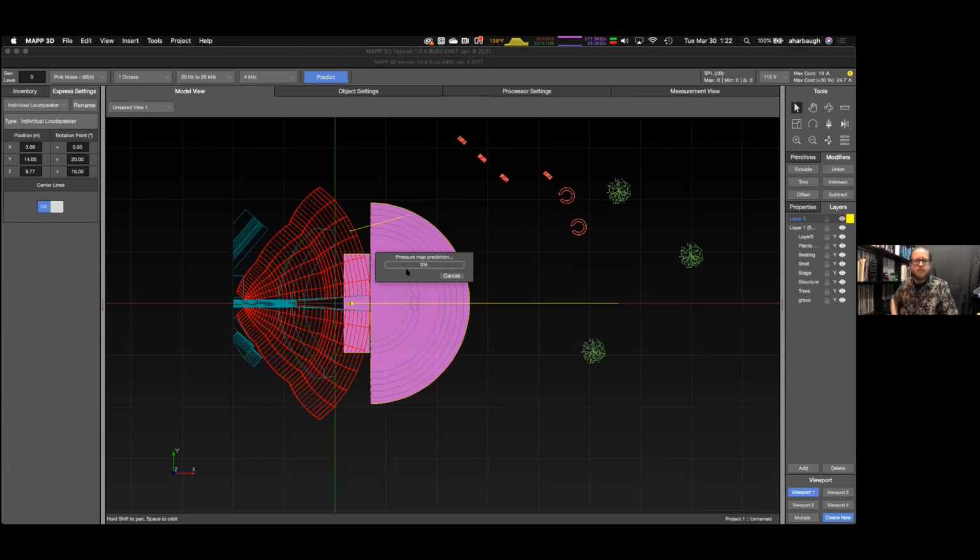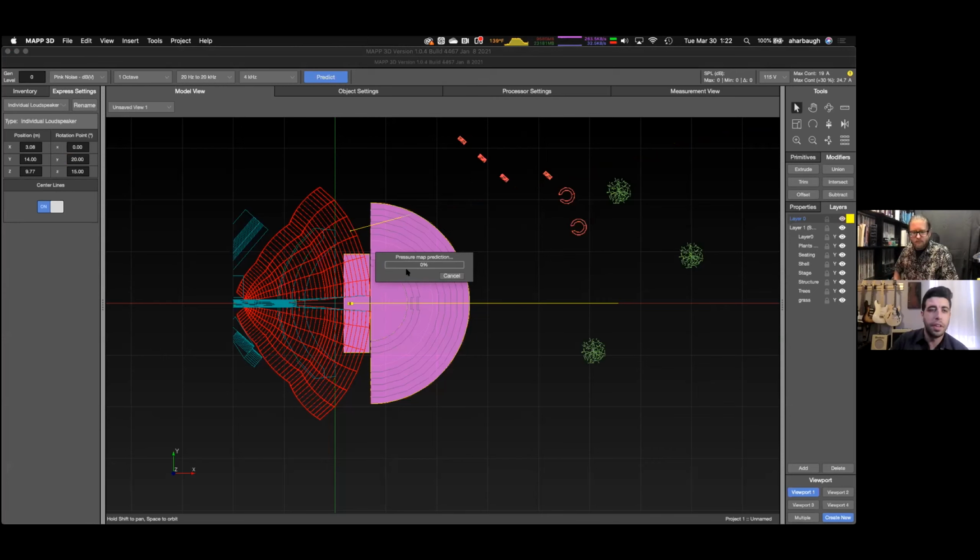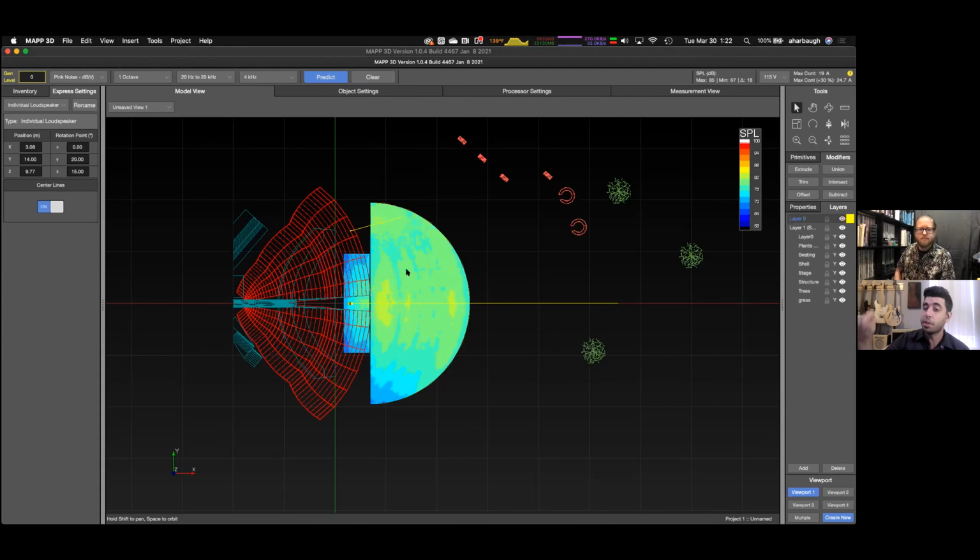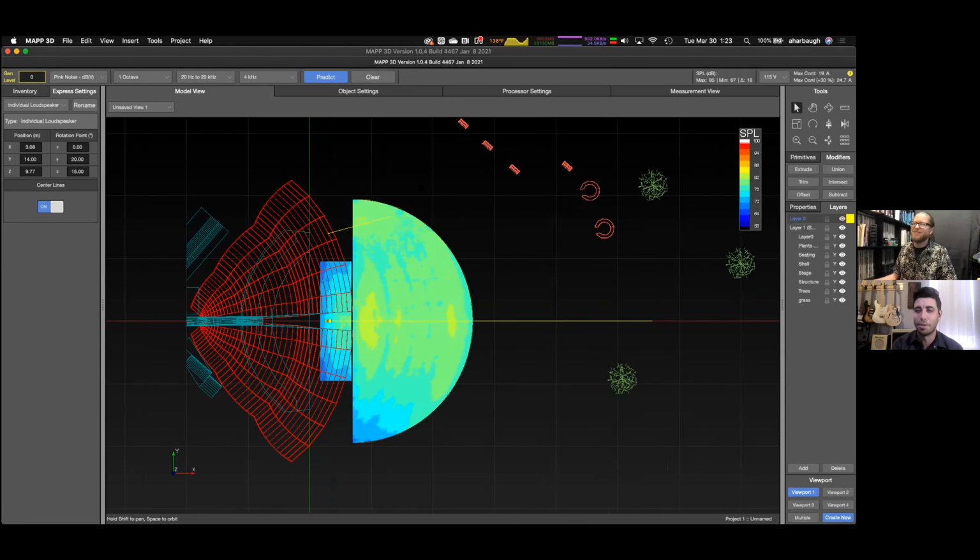Alex, while that's happening, you mentioned before that in express settings, you could use your up-down arrows, for instance, to move position or even rotation. Is that correct? So you can kind of see the center line moving. Is there a way to set the increment at which that goes? Currently, it's in 1 degree increments. Okay. In future versions, we're hoping that that can be maybe shift modified to be decimal increments or something. Sure. But currently, yeah, that is in 1 meter, 1 foot, or 1 degree increments currently. A lot easier than typing random numbers and hoping that it ends up on the right plot.